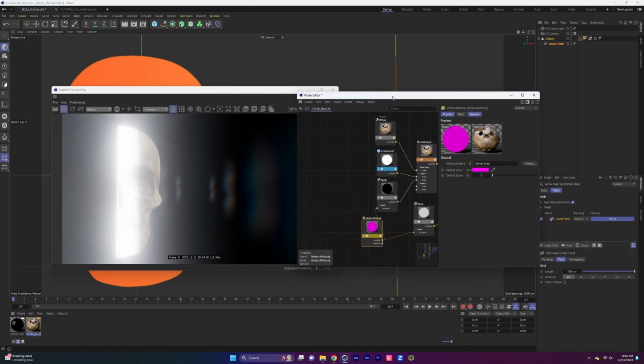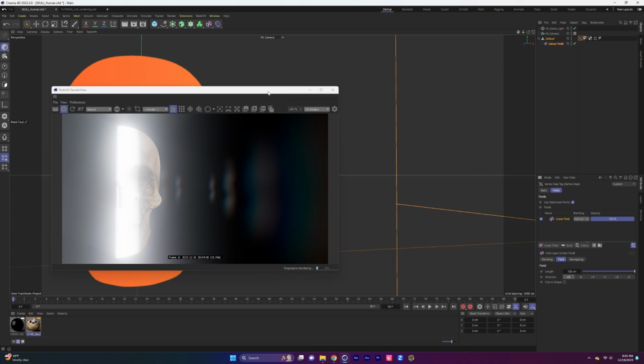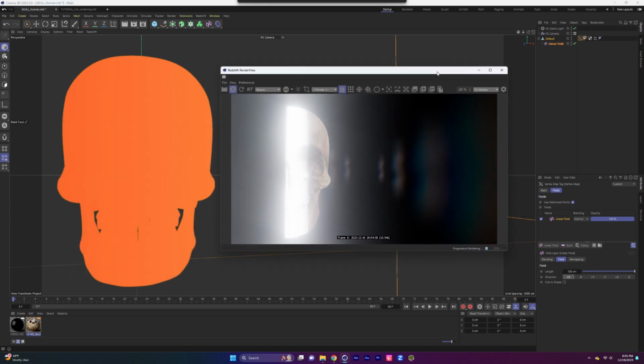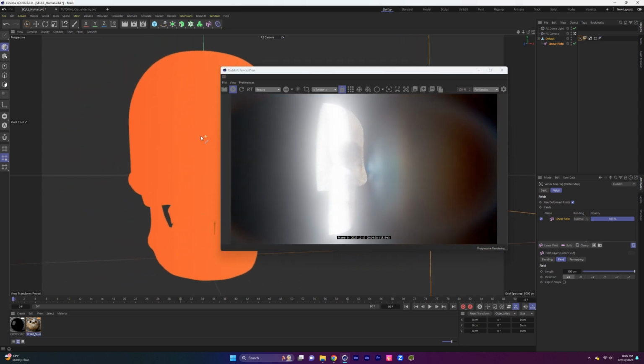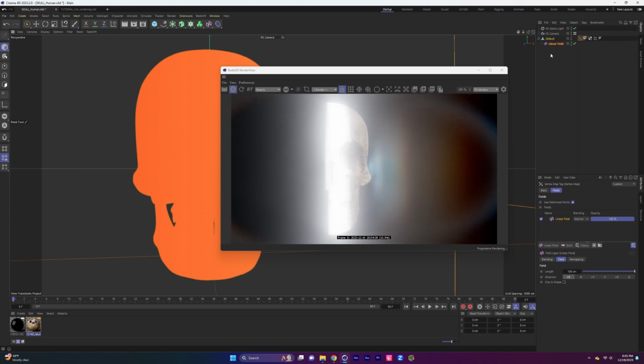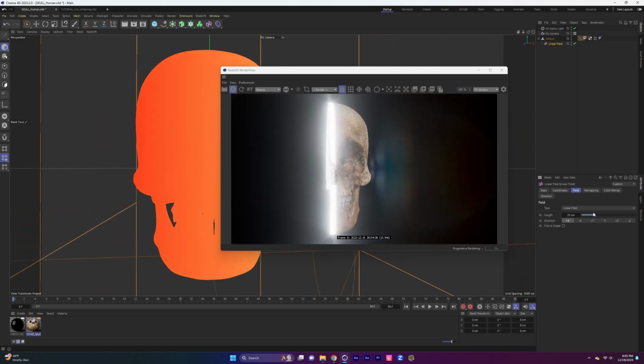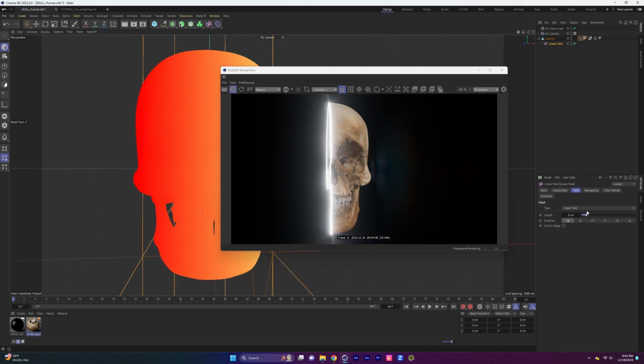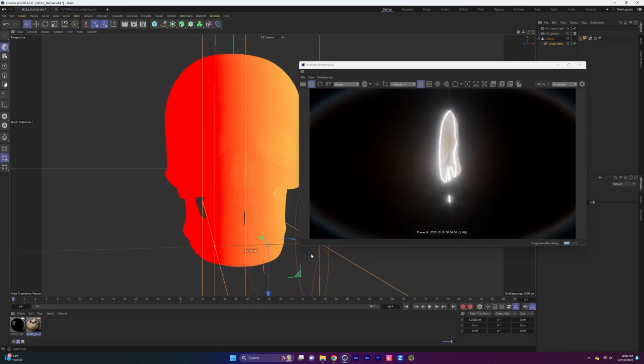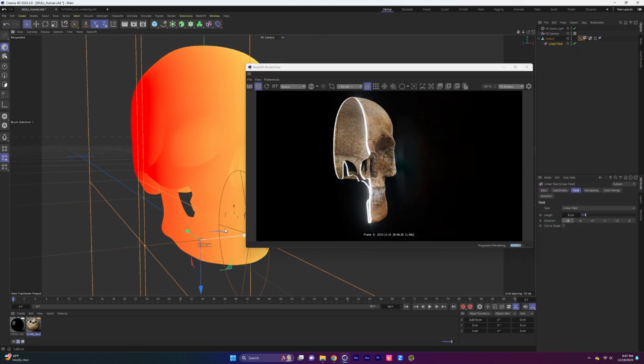Now we can see that the scale of the edge illumination has increased due to dropping this setup onto a different model. Sometimes it's going to vary depending on which model you're using and the size of the model scale. So all you have to do to adjust this is select the linear field and slide the length slider back until you get a desired result. Something like that. Now you can slice and dice however you want just by moving the field through it.